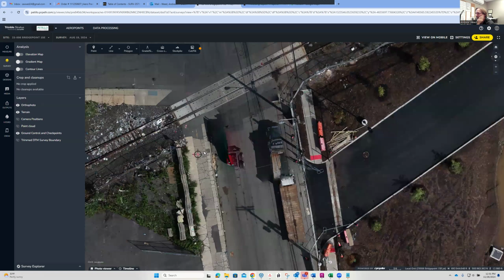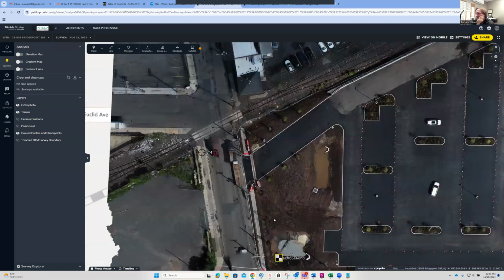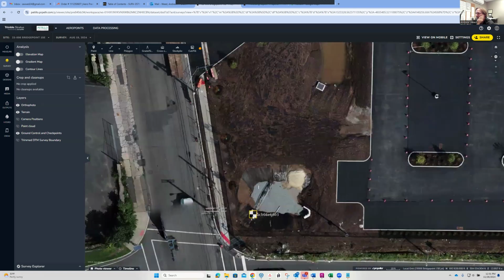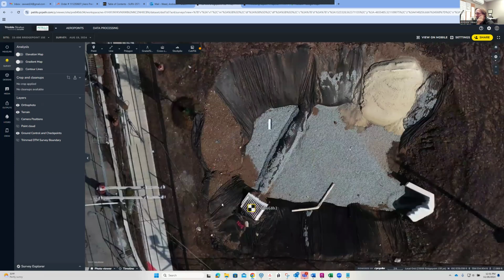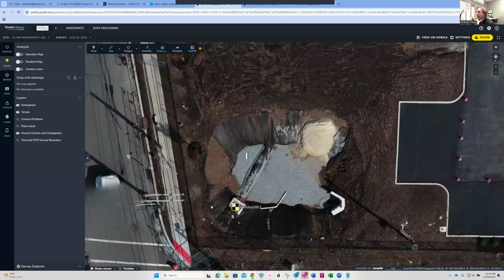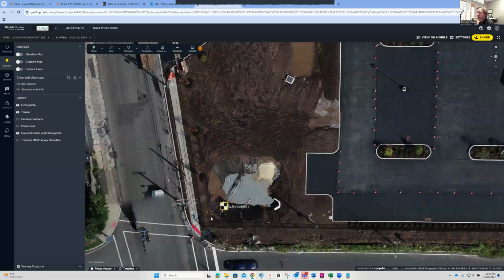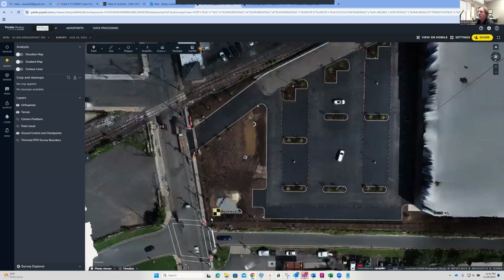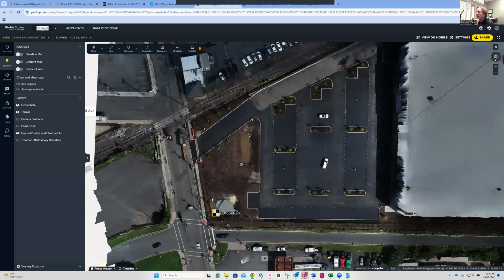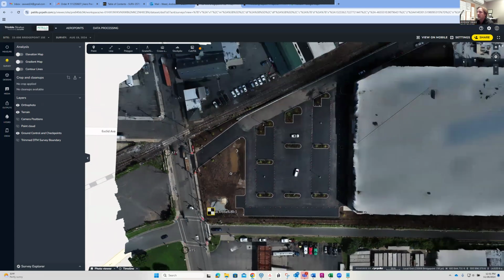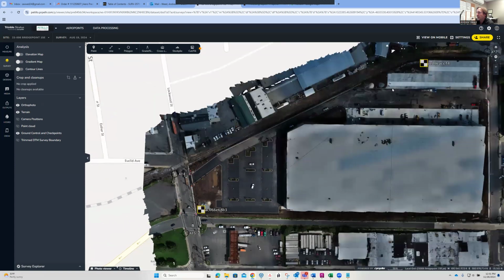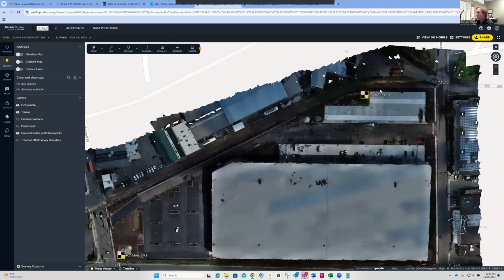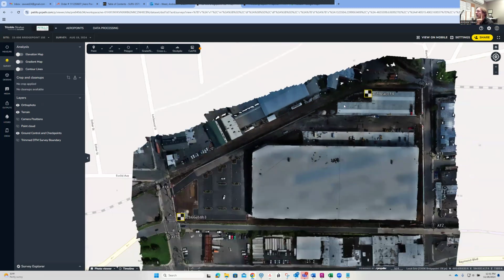And we also have actual GPS located points. These points themselves actually collect GPS data so that they can rectify their location, which is good, especially if you have a site in the middle of nowhere and you don't necessarily have site coordinates, but you want it to be as close to the real world as you can get. This will get you in the ballpark. It's not survey grade, but it gets you in the ballpark. And plus, when you have a pair of them working together, see, we had two arrow points, it gets you that much closer.